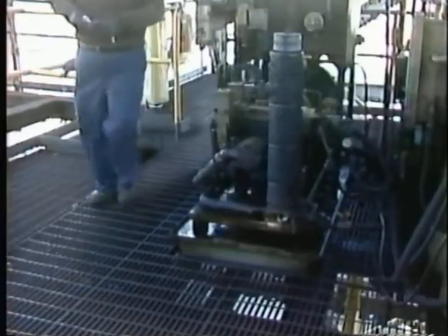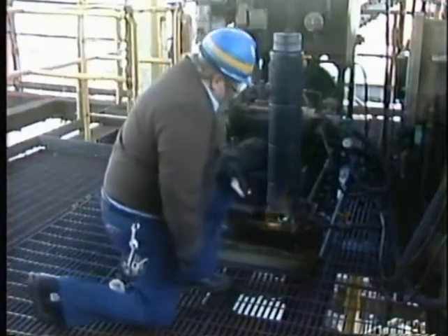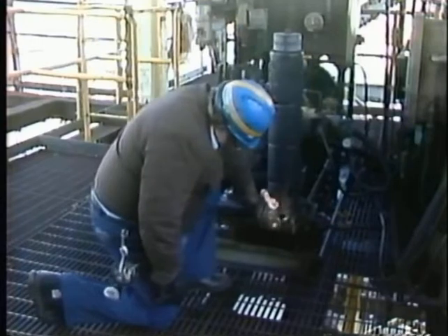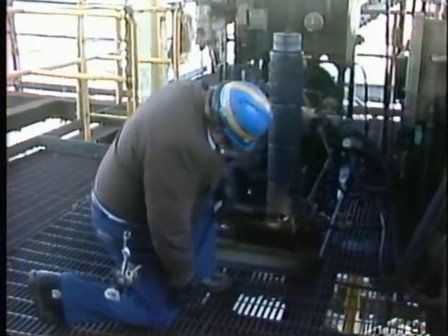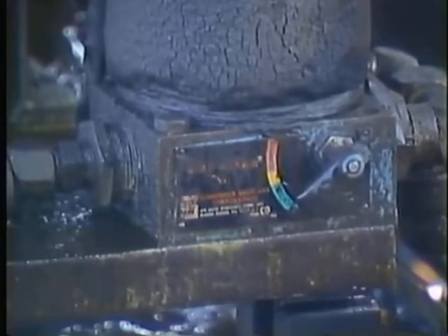Another component to check on a hydraulic system is the filter or strainer. Filters or strainers have to be checked to see if there are buildups of dirt and other contaminants which can restrict the flow of fluid. Some filters and strainers can be cleaned, while others use replaceable cartridges. In some cases, they're replaced on a scheduled basis. This filter has an indicator that shows an operator when it needs replacing.